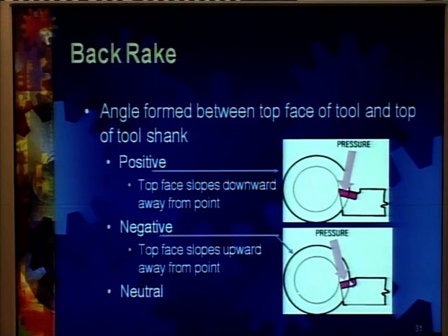But by doing this arrangement, or by making this tip slope in this direction, although the sharpness of this tool has been decreased a bit, the strength and the ability to withstand the pressure and the toughness of the tool have been increased, and as a result now the tool will be able to withstand the intermittent loads as well as the very hard or the very high speed loads without any threat of breaking away.